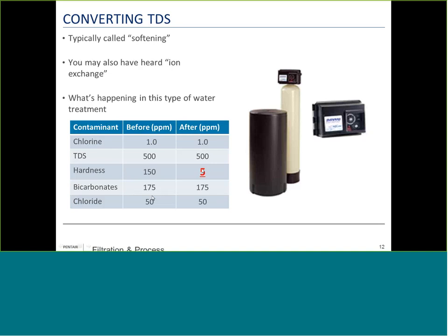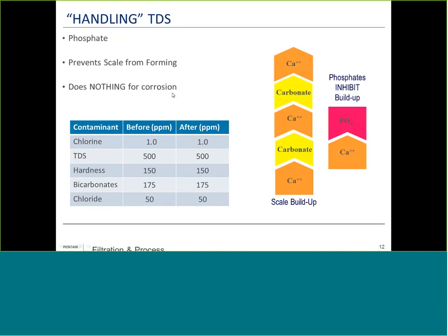All we're doing is adding a chemical that sequesters calcium and keeps it in water, along with magnesium and iron and other +2 metals. And when it does form scale, it forms a phosphate scale, not a carbonate scale. And this scale is a soft, mushy scale that breaks apart and dissolves easily.